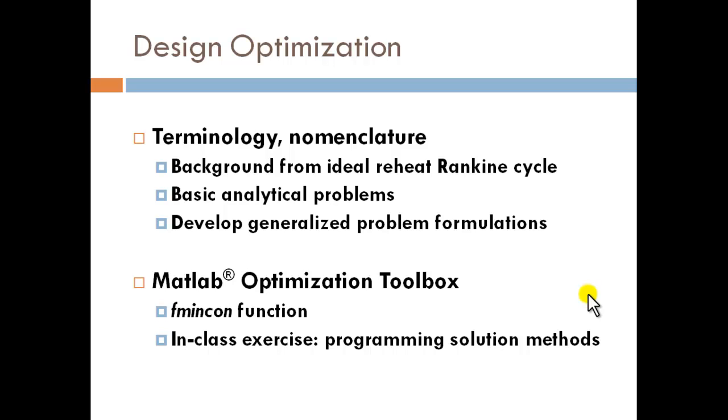I want to come up with the equations that will be used not by you technically, but by the MATLAB optimization toolbox. I want you to know what's going on behind the scenes, if you will. And the function that we're going to be using in MATLAB is fmincon. It's a minimization function that has constraints, fmincon, and f is what's known as the objective function.